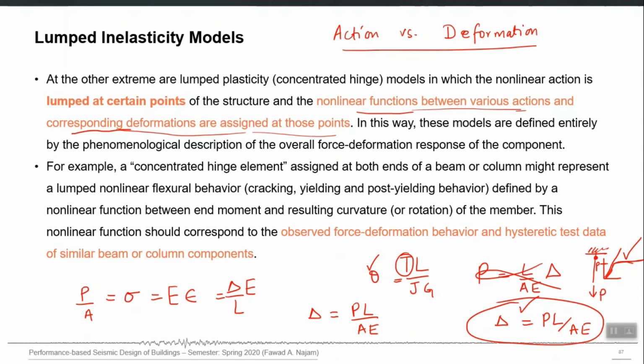Right? So the beam bends, and when we take a tangent at any deflected shape, the horizontal angle of that tangent is the rotation. So the more bending moment is applied, the more the beam bends and there is more rotation. So we can directly put our own moment versus rotation behavior at certain locations in our beams, so that we tell the program that this is the moment at which the beam will yield and how it will behave after yielding, depending upon how the line is behaving.